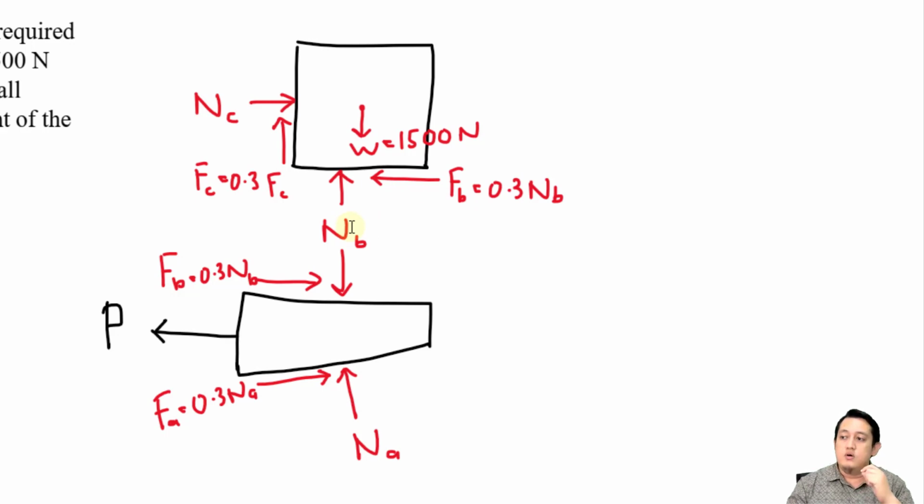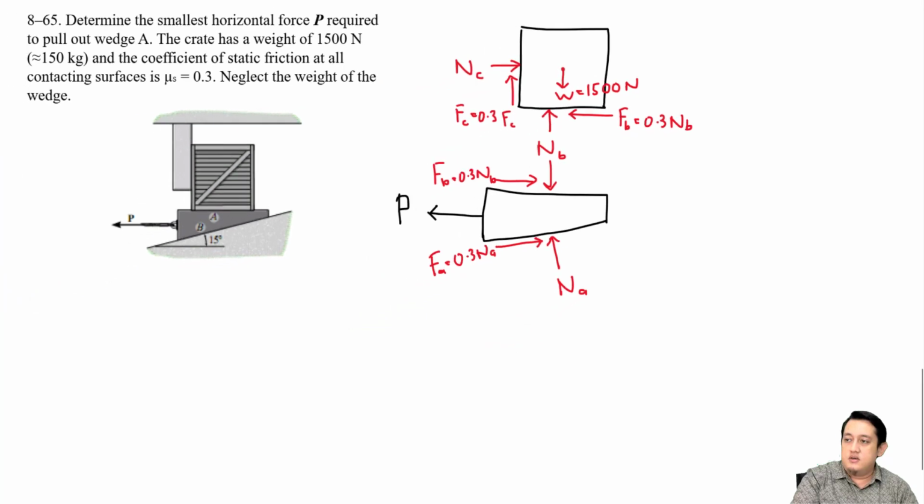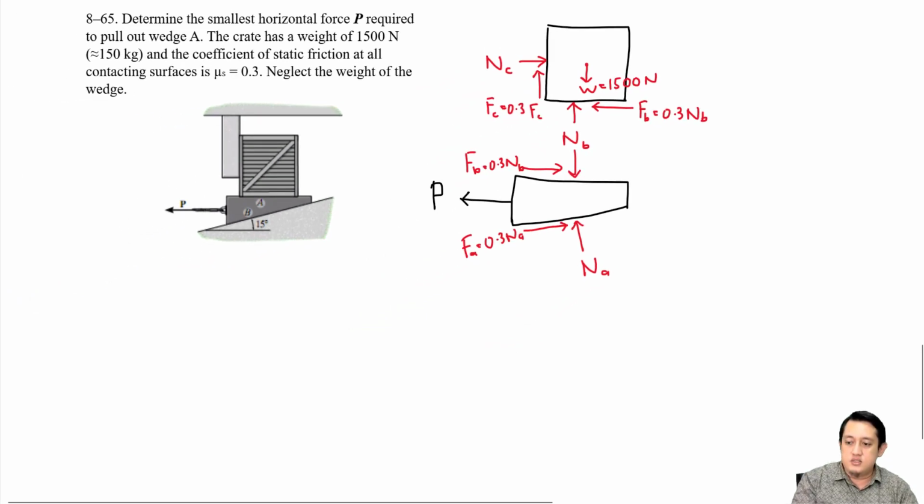Before we start, as you can see here, we have a lot of forces in a lot of directions. Before you start writing down the equation, it is better to draw all the forces again and put them on this point.